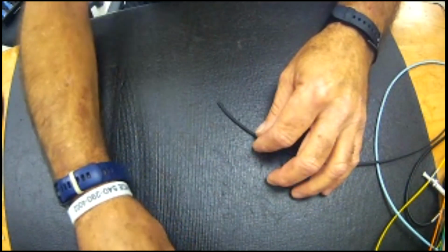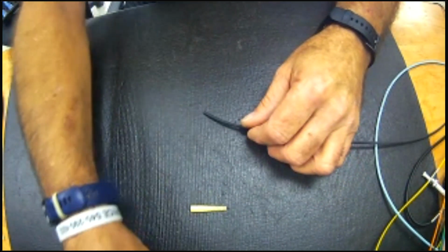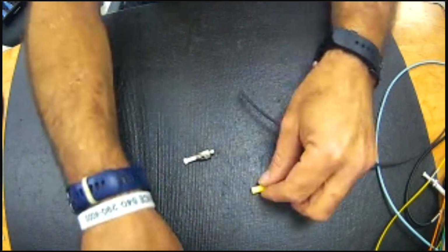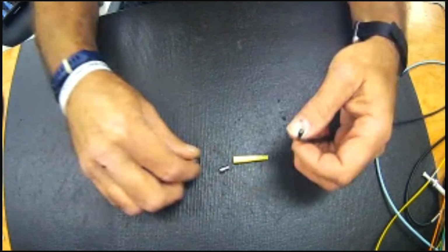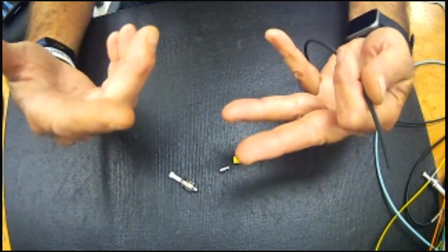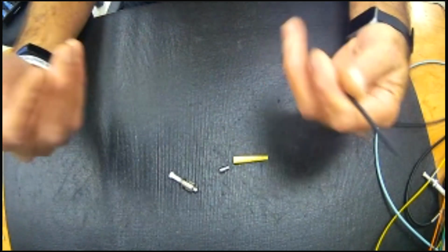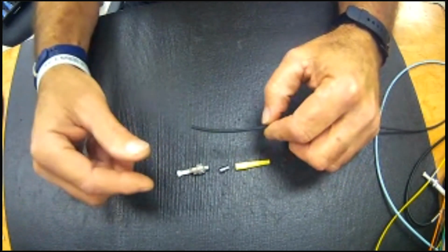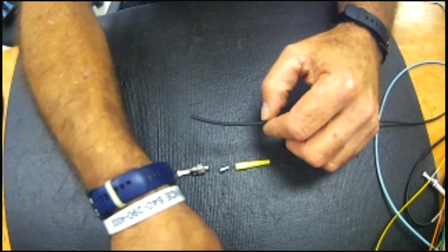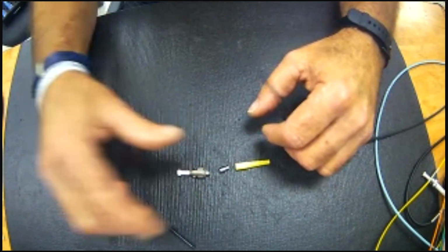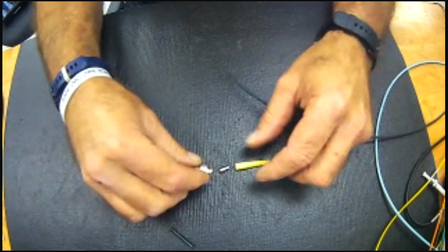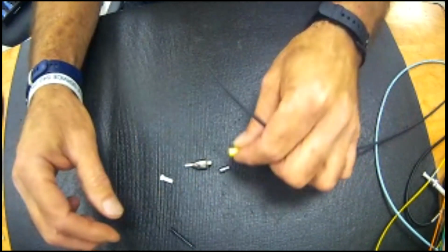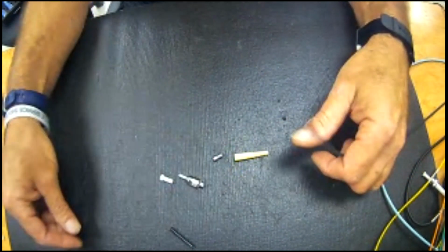A connector I'd like to show you is the ST. The ST is most common to the field connector. You'll find that in your stadiums and your patch bays at field venues. Not as common as on your BSPs, but it is the one that is most like a BNC connector. It comes in 3 pieces: a boot, a crimp sleeve, and a body.